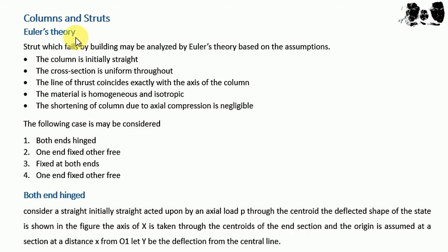Can we give an example of struts? Yes. If we talk about a wooden or timber structure, or bridges, or complex structures where diagonal members are needed to transmit diagonal loading or give better stability to the structure, then struts are used.